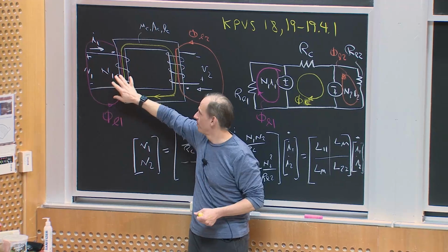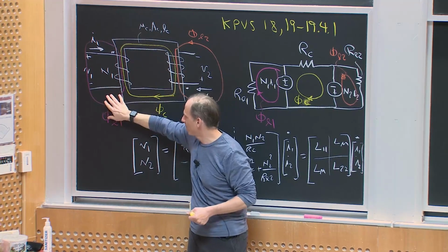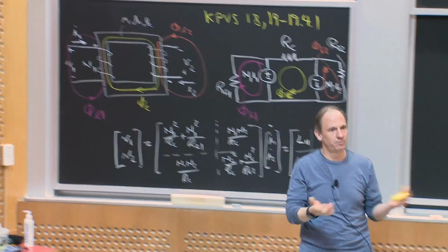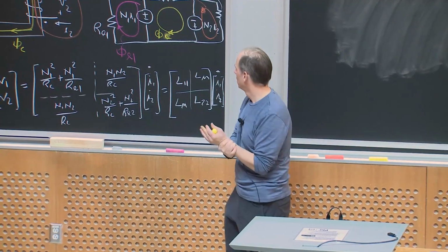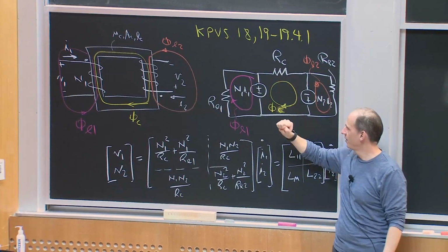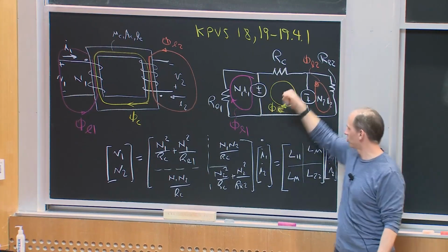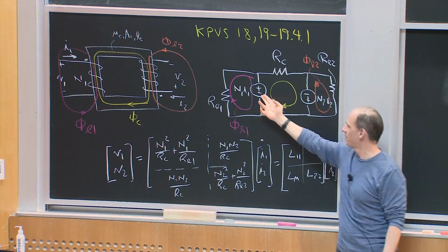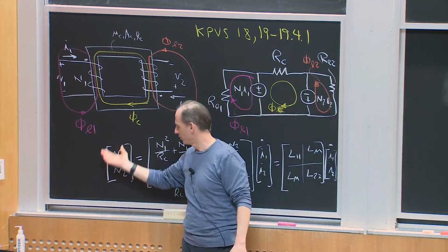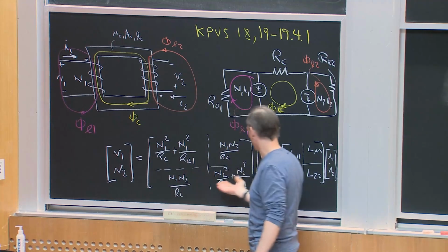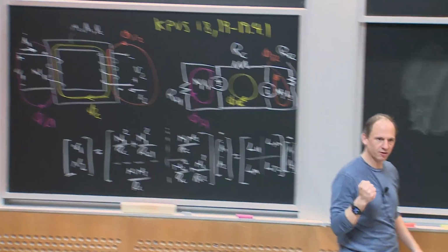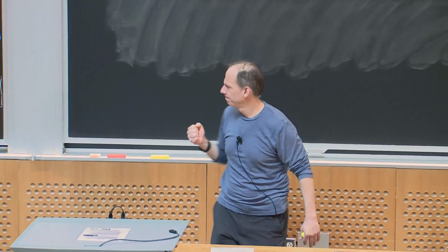Now, when the permeability of the core is really high, the amount these other components matter is less, but nonetheless we incorporated them. And then what we did was we created a magnetic circuit model, and then worked back to what the flux linkages were for these 2 MMF sources. And from that, you can work back to the voltage, which is the derivative of the flux linkage, and we can work back to the relationships between the voltages and the currents at the 2 terminals, okay?